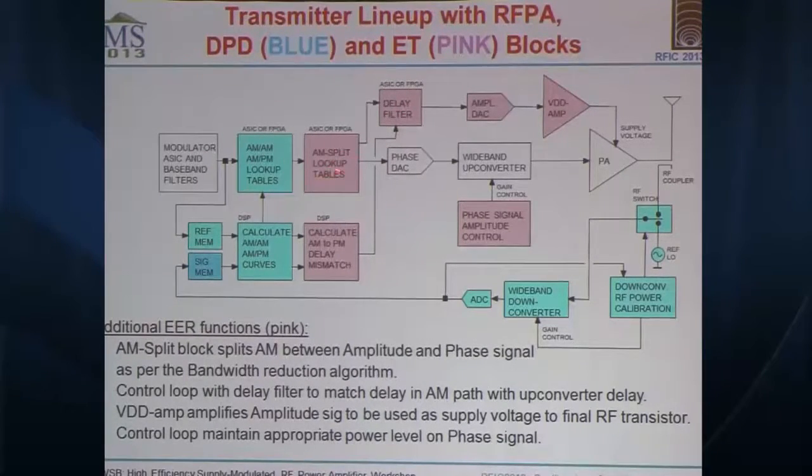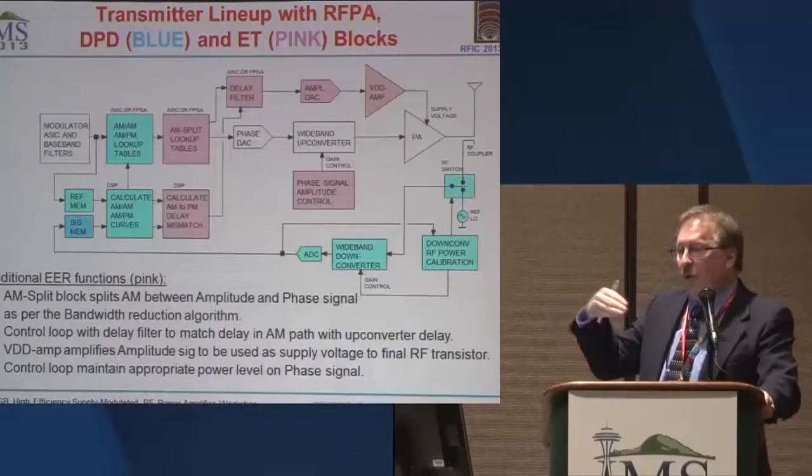So on this side, we actually have a CORDIC to go into magnitude-phase space. We'll use that to build the table that builds the envelope signal. And then we'll have a CORDIC on this side to come back to IQ to run into the up conversion chain and out. Here we'll also have a delay filter that allows us to do the subsample shifting forward or backward in time.